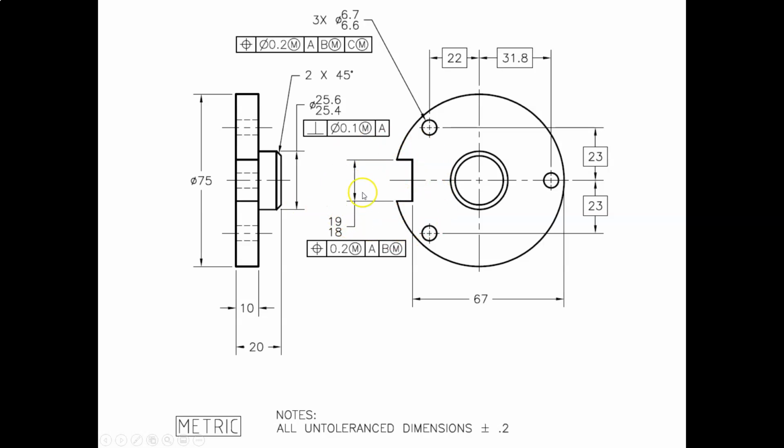The rectangular notch cut out, again, we're dimensioning it with a tolerance. So it's 18 to 19 millimeters across here. All right. And the depth of the cut in this notch is not, again, explicitly defined in this direction. We see it from the back surface, so it's 67 millimeters from here to here.